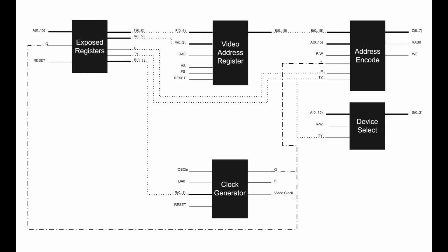Where the logic is layers deep, the number of clock ticks to fully propagate a change can cause problems. Some of this can be mitigated with combinatorial logic that propagates faster than latched values, but the timing on these circuits has to be then constrained to make sure the signals arrive in order. I can improve the situation further by doubling the master clock. This narrows the timing gap for propagation, but means the main timing state machine needs twice as many states, all of which is doable with a little effort. Once again, as with the VDG, that's it. A surprisingly simple design, at least if you ignore the ugly complicated bits of just 5 functional parts.